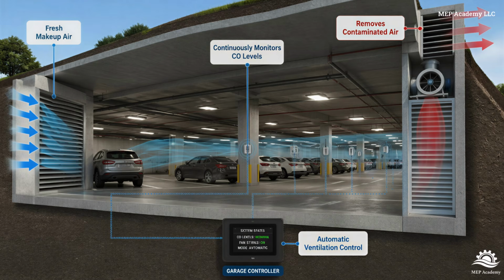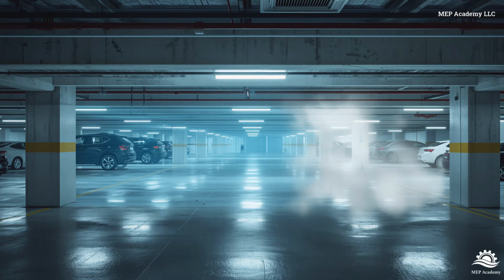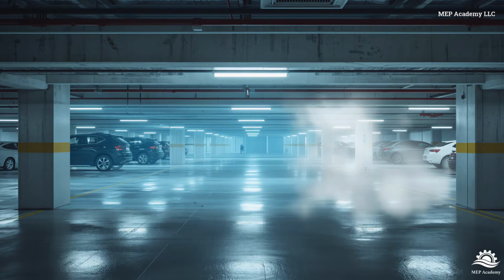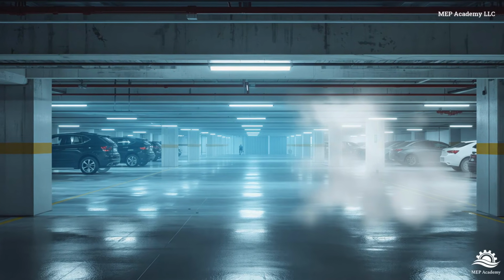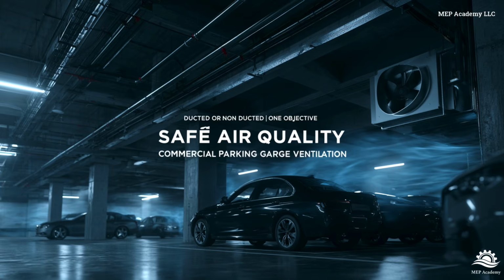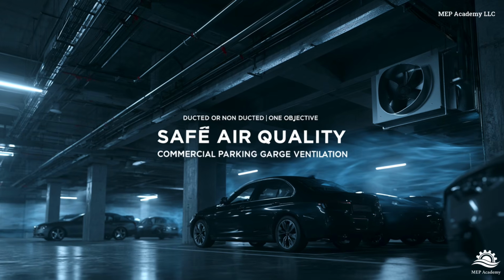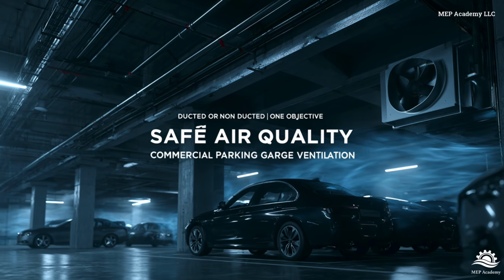Summary. Garage exhaust systems protect occupants by preventing the buildup of dangerous carbon monoxide inside enclosed parking structures. They accomplish this by continuously monitoring carbon monoxide levels and introducing outdoor makeup air while exhausting contaminated air to the outside. Whether the system is ducted or non-ducted, the objective is the same: maintaining safe air quality for everyone using the garage.